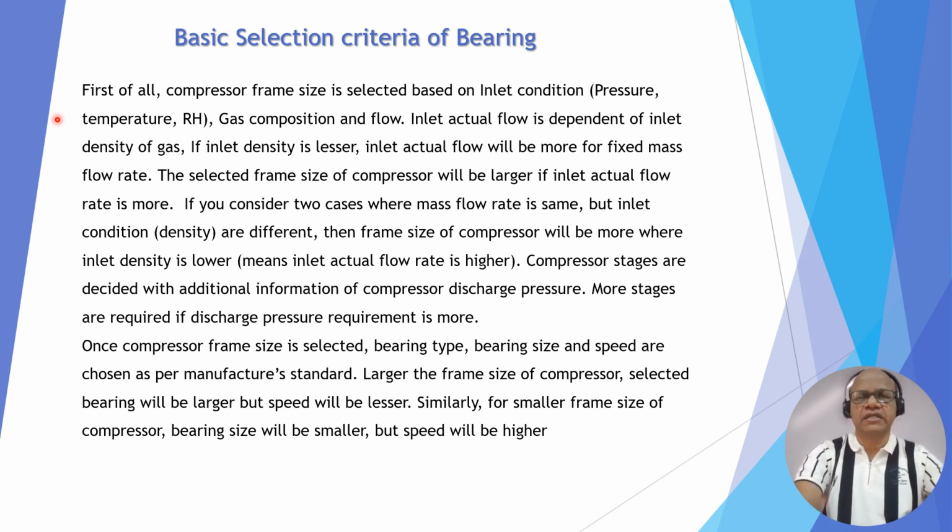What are the inlet conditions? Inlet condition means pressure, temperature, gas composition, relative humidity, and flow. Inlet density is dependent on inlet condition. Why? Because if inlet pressure is more, density will be more. If inlet pressure is low, density will be low. Similarly, if inlet temperature is high, density will be low. If inlet temperature is low, density will be high. Similarly, if the gas composition is denser, density will be more, and vice versa. So density is dependent on inlet condition.